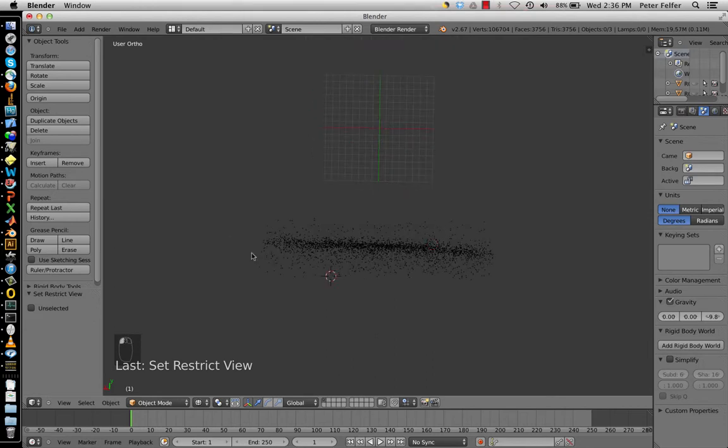And so now we've got the 3D cursor there. And if we add our analysis object, it will actually edit what a cursor is. So if your cursor is not right at the center, press Shift S and go cursor to center. Then the origin of the local coordinate system of your analysis object will be at the origin of the world.